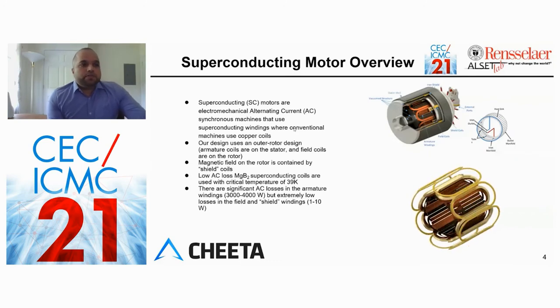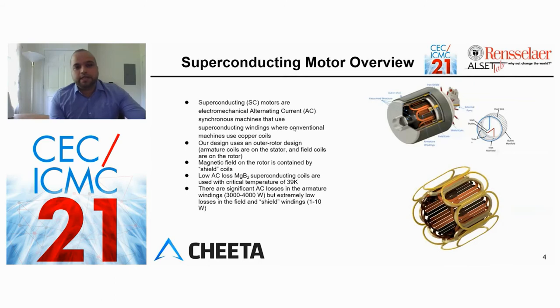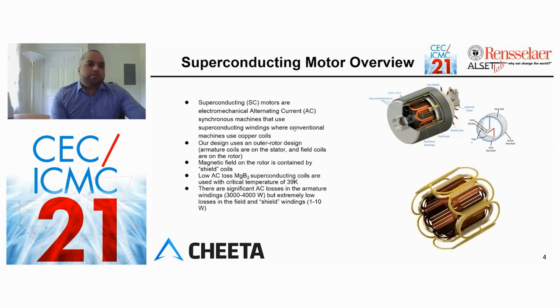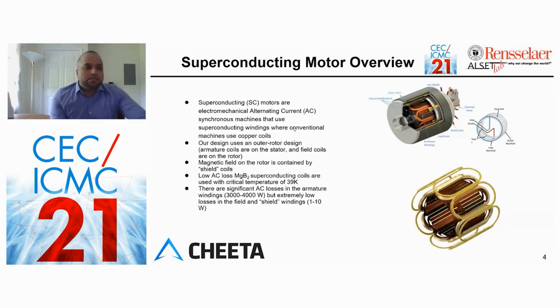Here is an overview of the machine that will propel the aircraft. Superconducting motors are electromagnetic alternating current synchronous machines that use superconducting windings, where conventional machines use copper coils. Advantages include reduced size, lower rotor losses, and better weight to power capacity ratios. It is necessary that the superconducting motor operates below a critical temperature, or it would revert to its normal phase due to exceeding of current, temperature, or magnetic field limits.